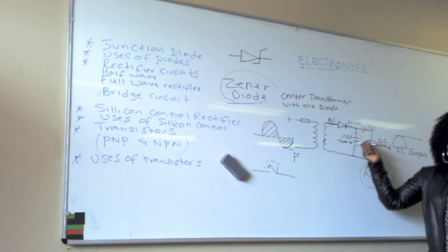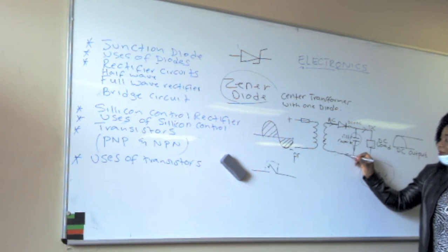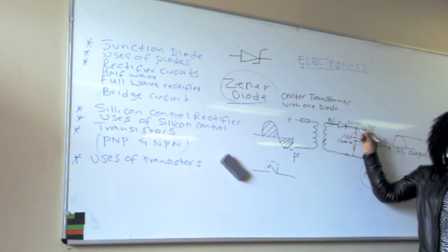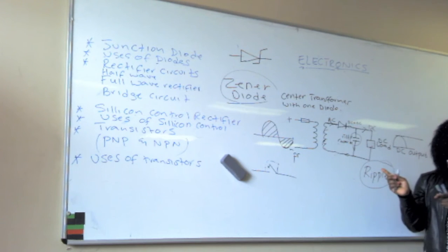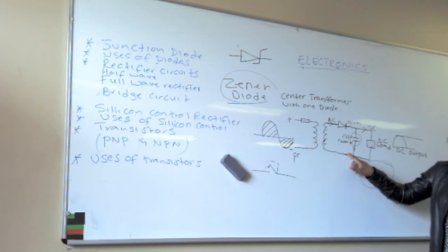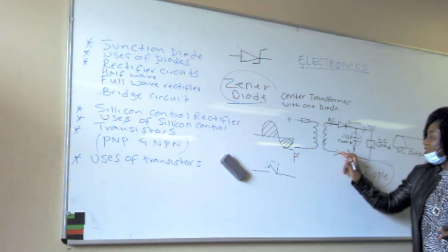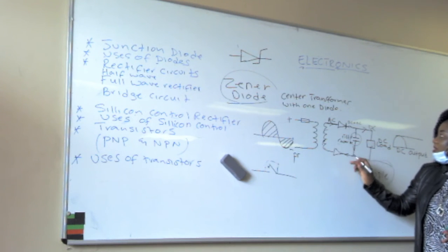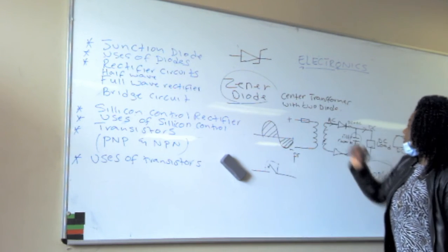What happens to the stored charge here, which is the AC charge? This capacitor is going to release the charge and send it back to the transformer. This charge that the capacitor stores here will be released down here and back to the transformer and again be rectified. Can you see? To be rectified further. That is how it should be done. Then, if we say it's now a two-wave rectifier or two half-wave, it's going to change. It will be two diodes. Two diodes is a full-wave rectifier with two diodes.